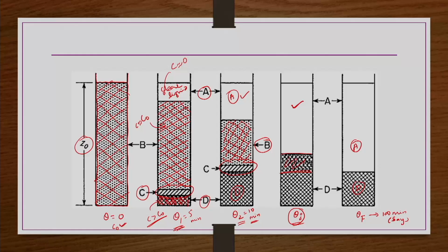In between there will be some region which is very turbid, that does not have a connection or appearance; it does not look like a C zone or a D zone in appearance. So, that is a point where B zone completely disappears, and C zone is mixing up with D zone, or slowly it started decreasing and then there will not be C zone at all after that also. Then we get this clarified liquid and then concentrated sludge as two separate phases.